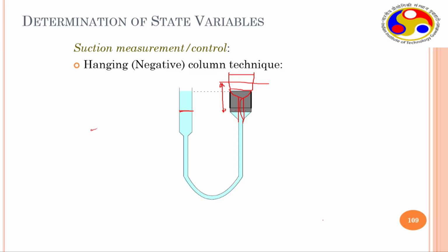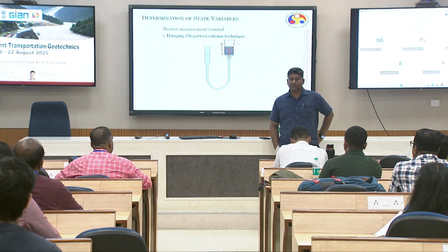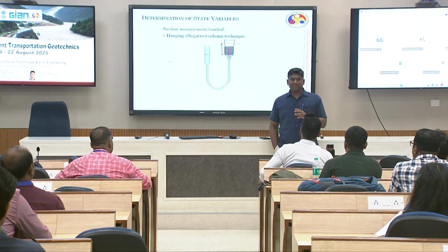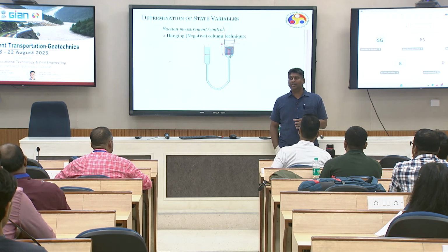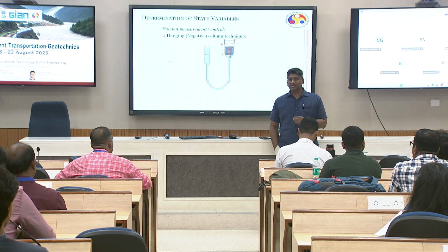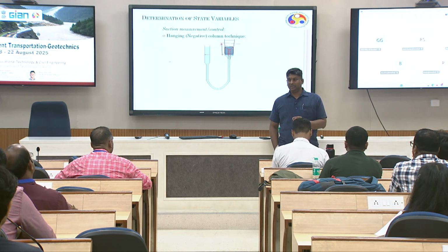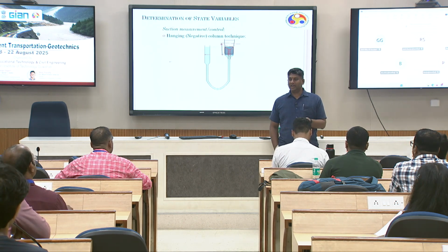Yesterday the hanging column method was shown in the laboratory. Hanging column method, or negative column method. Although the setup appeared to be slightly different, it is a wonderful method to evaluate suction values at low suction values, especially good for sands or something else.